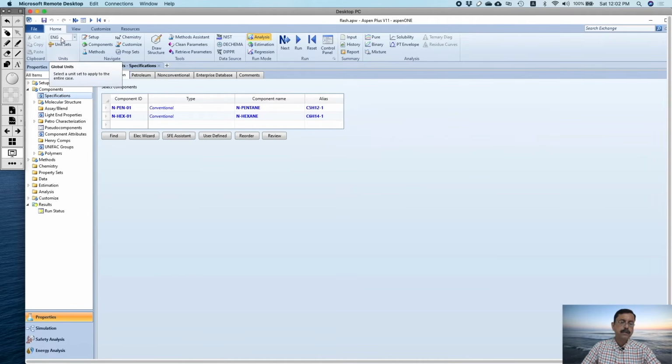English unit was given, but you can change the unit over here. Instead of English unit, you can write metric, or metric with C bar. Temperature is in centigrade, pressure is in bar, or purely SI unit. So everything will be in kg, kilomole, Kelvin, etc.